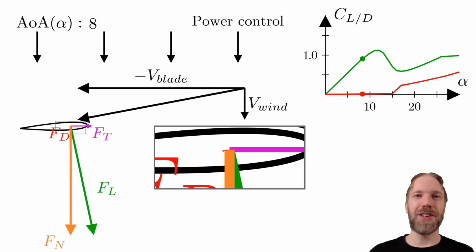As a final case before we leave the single airfoil, let us think how we can control the forces to avoid too large tangential forces when the wind speed increases. This is very important for wind turbines when we have too large wind speeds. I will now illustrate the concepts used for wind turbines for this individual blade. The first concept we are going to look at is passive stall. This was used in the early wind turbines before more advanced methods came.